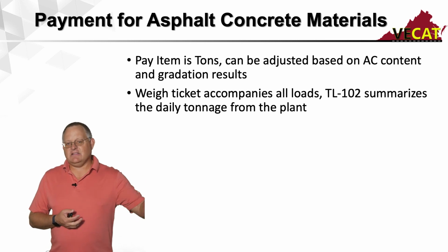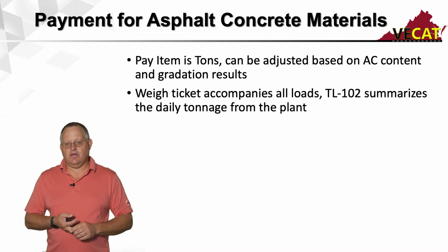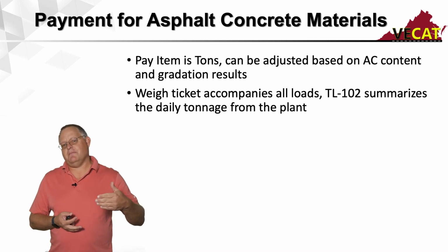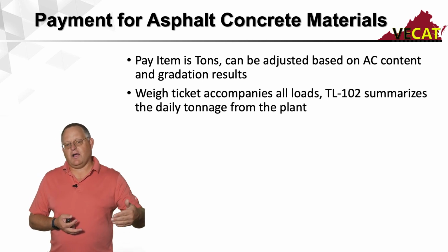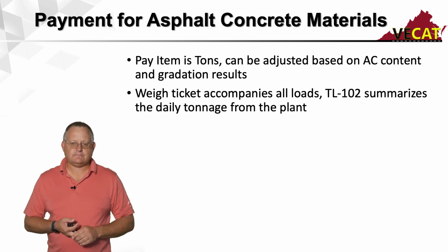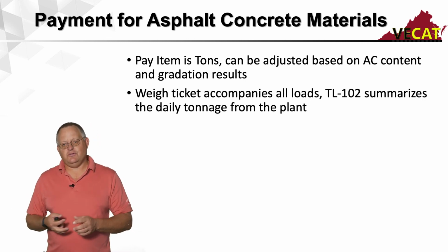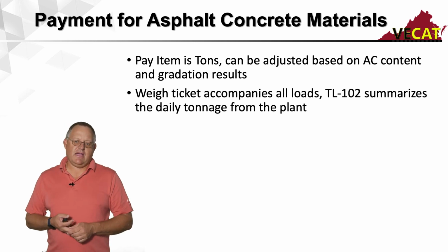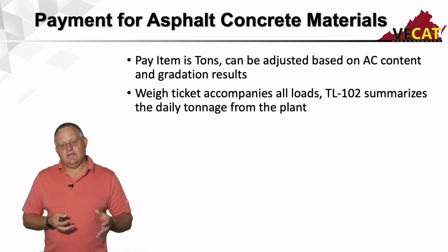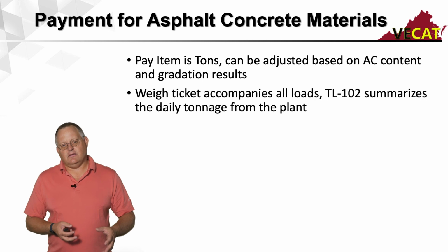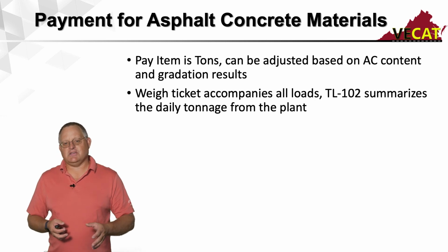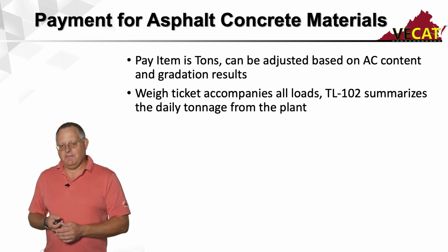But that weigh ticket accompanies each and every load that goes out, because we want to make sure the right product is going to the right project, and it has the right tonnage. At the end of the day or the end of the shift, we also have those TO-102s that summarize all the daily tonnage sent from that plant to that project, because that's how payment will be determined.